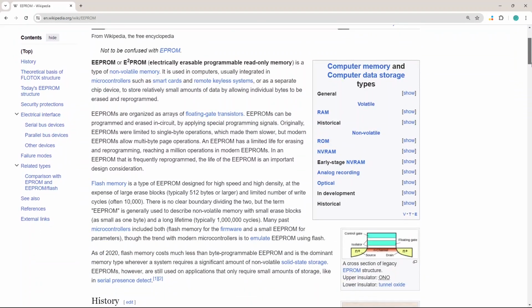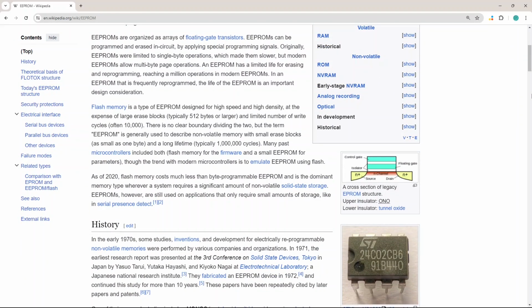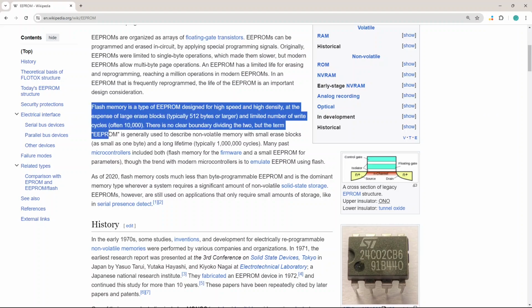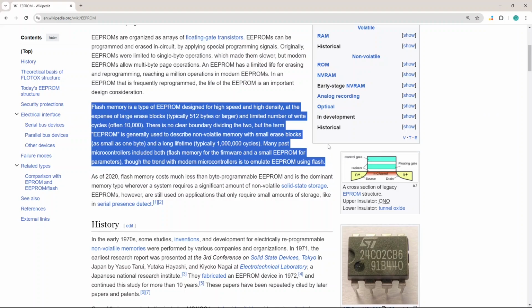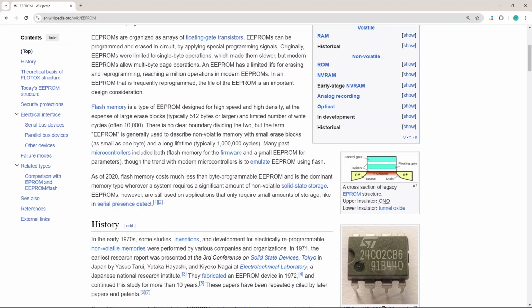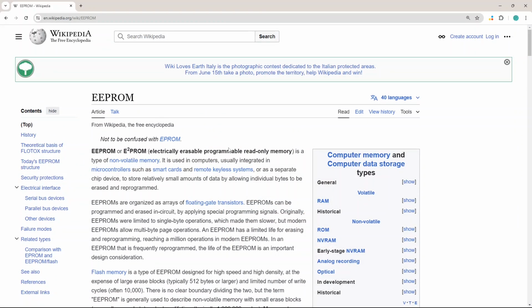Anyway, EEPROM and flash have two important differences among others. EEPROM is designed to allow a higher number of writing cycles than flash. And EEPROM, again usually, needs a quite shorter time in the erasing and writing cycles. So, avoiding going too much into details of EEPROM and flash, I made a specific video about it, a link to it is below here in the video description.